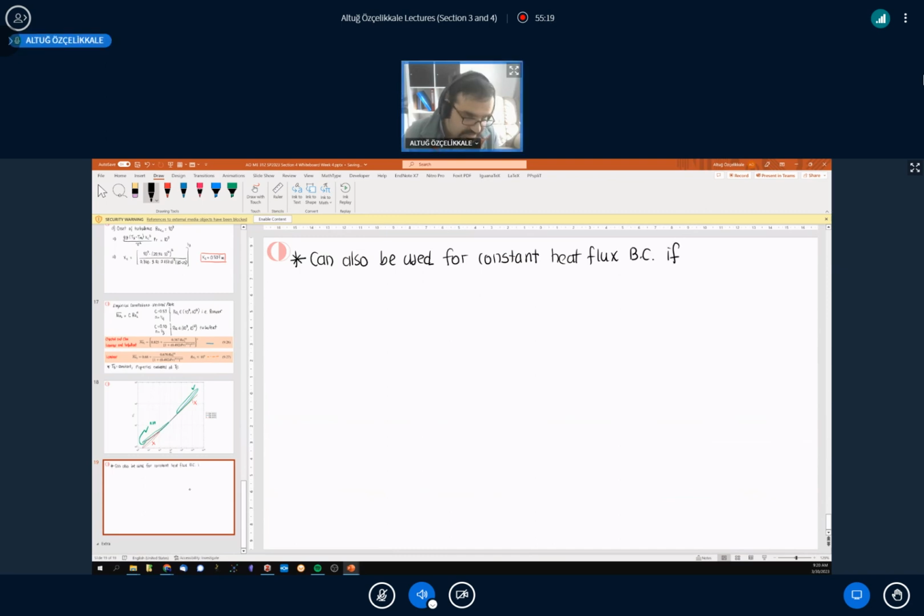However, notice that things are a little bit complicated because our governing dimensionless groups include delta T in them. You need to define the delta T, that's Ts minus T infinity or vice versa, as a function of location. So that temperature is going to depend on the x direction in that case. And we are going to pick the location of temperature at the middle of the plate.